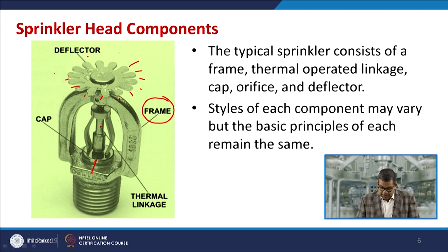Now remember, if the thermal linkage is not functioning properly, there may be a chance that at the time of a fire it may not actuate, or sometimes when you are working in a safe environment it may be actuated, and property or economic losses would be on site. That's why there should be proper synchronization among the deflector, cap, frame and linkage. The style of each component may vary, but the basic principle of each remains the same. Now let's discuss all four ingredients.